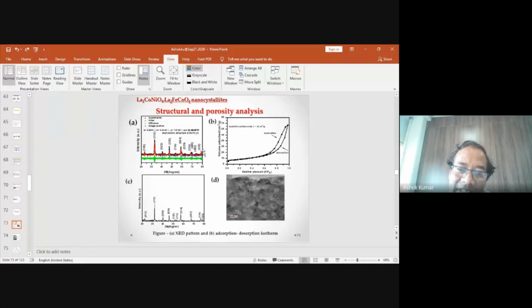In a crystal, we have a systematic and periodic arrangement of atoms. Look towards the cursor. Here we have a systematic and periodic arrangement of atoms, arranged like this. So this will look like a line. And then another one like this, a systematic arrangement. On this 2D screen we can only draw a 2D crystal, but real crystals are 3D. So one dimension you can consider perpendicular to the plane of the screen. That means every line, which looks like a line, is a plane. Every line, and the spacing between these planes is the interplanar spacing.